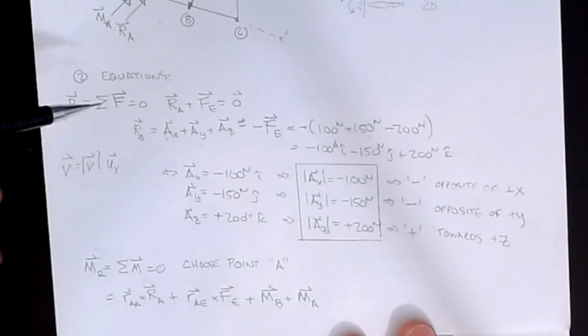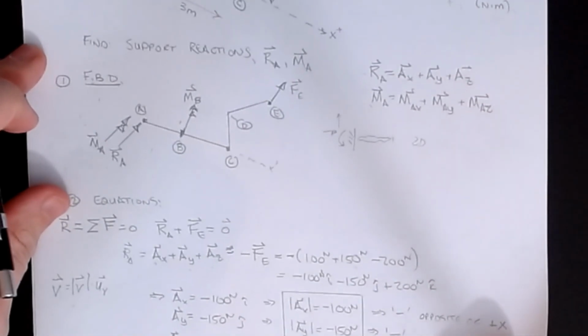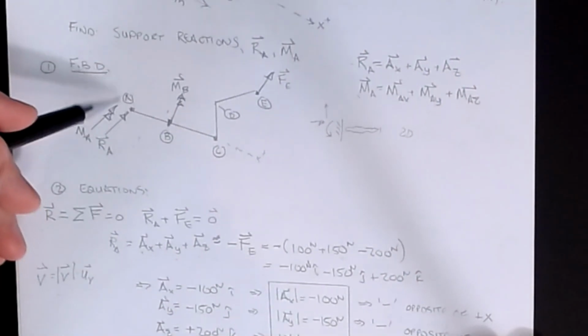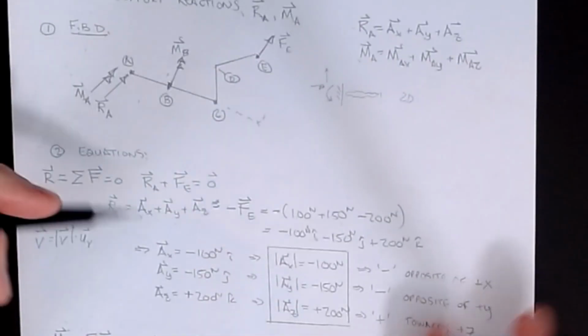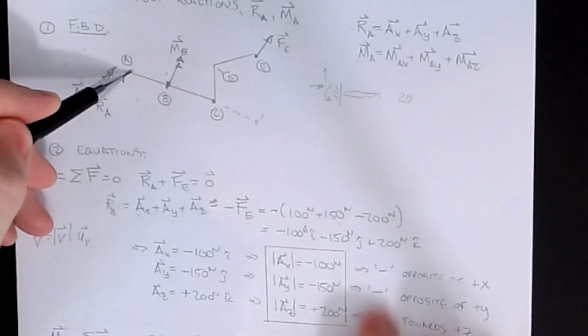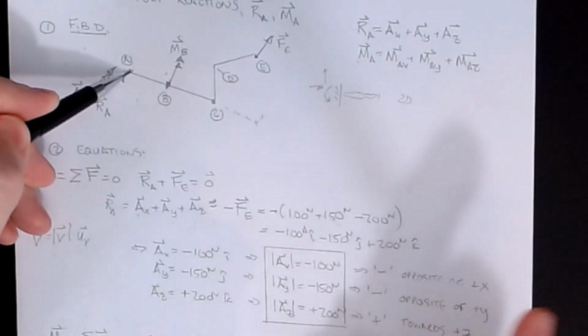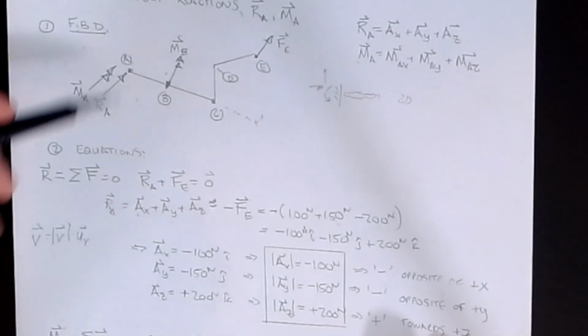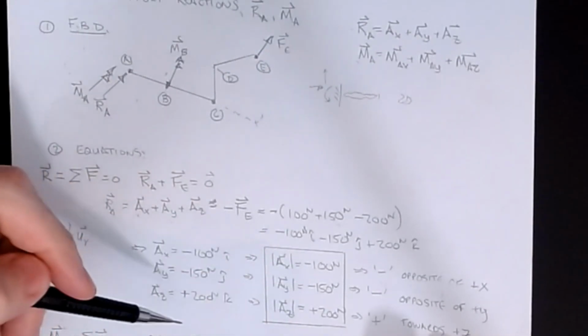So for this problem, again, often we look for places where the most unknowns are, okay, and at the beginning of the problem, the most unknowns were clearly at A. And one reason that I would choose the sum moment today is if we made a mistake in our calculations in the first part, say we had a math error, by summing moments here, I eliminate that from causing a problem in any future calculations. Okay, now sometimes you can't avoid having to reuse a calculation, but this is a chance to at least get the moment right, even if I screwed up the force vectors.